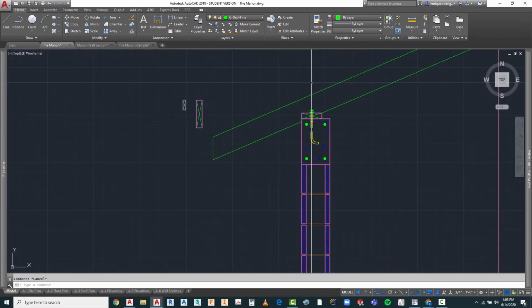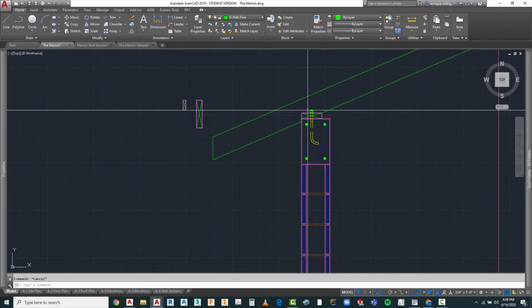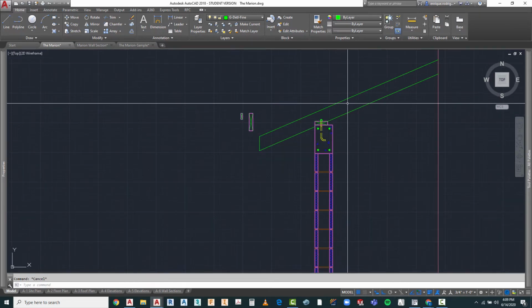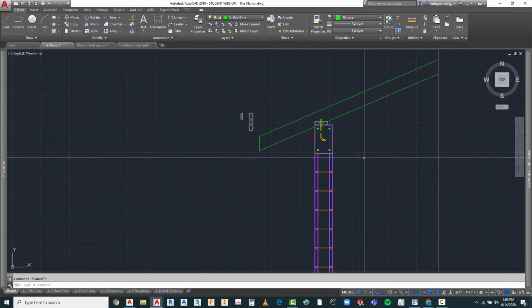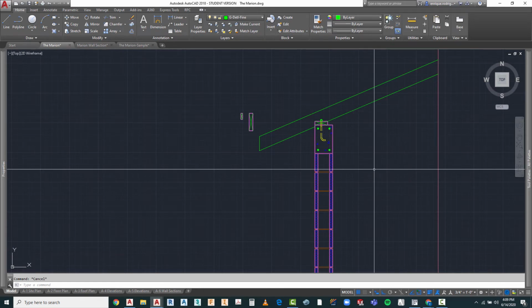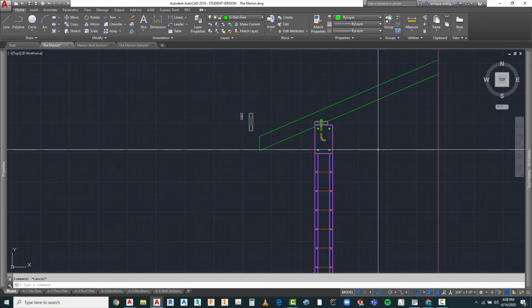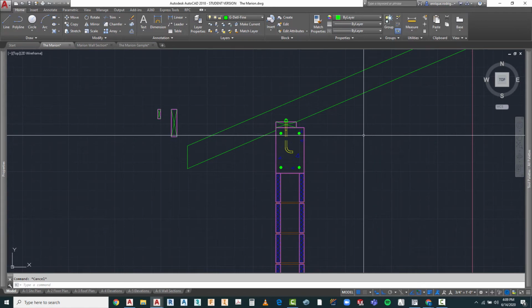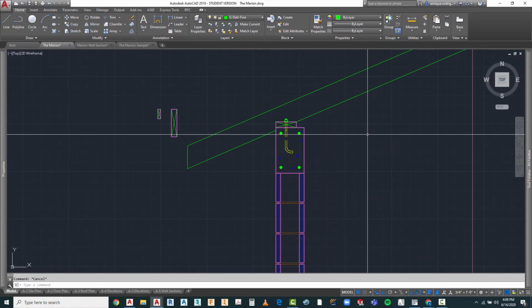Alright, so what we have right here is our rafters, then, located. These rafters are going to be spaced every 2 feet. Again, that may vary depending on what the structural engineers say, or the spans, or the size of the joist that you want to use, but that is very, very typical. Once again, dealing with the modularity of construction.